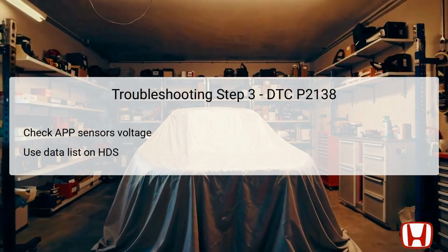It is crucial to ensure that both sensors are providing similar voltage signals, as this validation confirms their proper operation. If the voltages are the same, it signifies that the sensors are functioning correctly, and the issue may lie further downstream in the wiring or PCM. However, if there is a discrepancy between the two sensors, it indicates a malfunction that must be investigated further. This step closely examines the individual performance of each sensor, establishing a baseline that can help pinpoint the source of the error code more effectively.